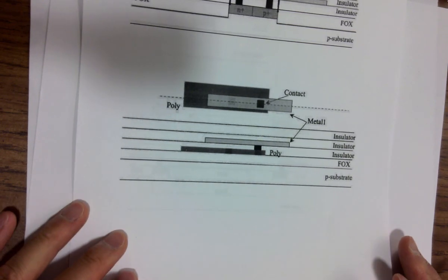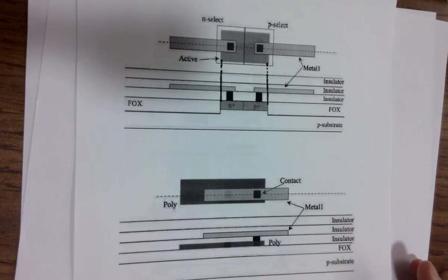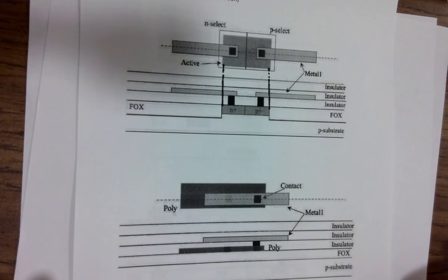When you're talking about lining up the n-select and the p-select so that you kind of overlap, if you're trying to make something like that, would you do the n-select layer first and then overlap with the p-select, or are you trying to really line those up in the center there?